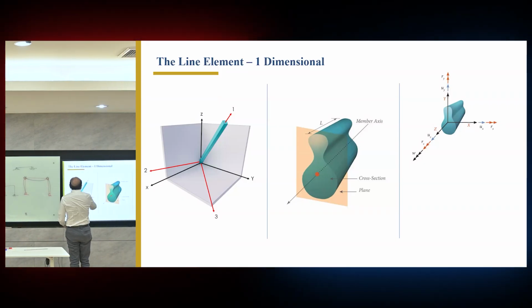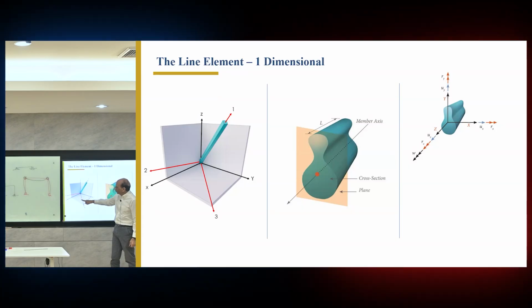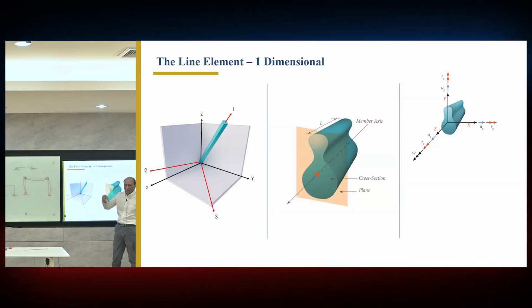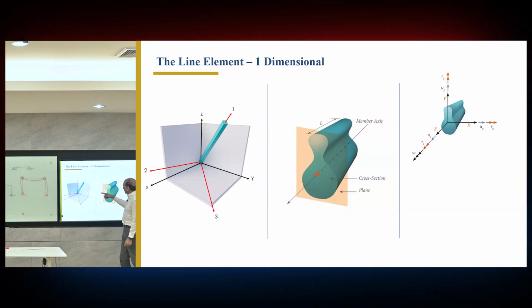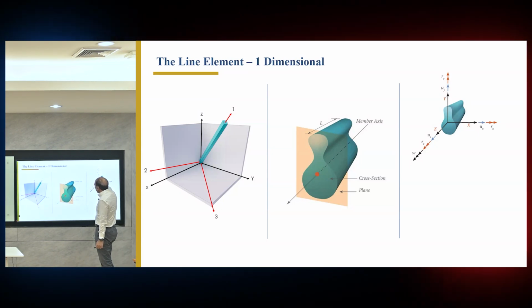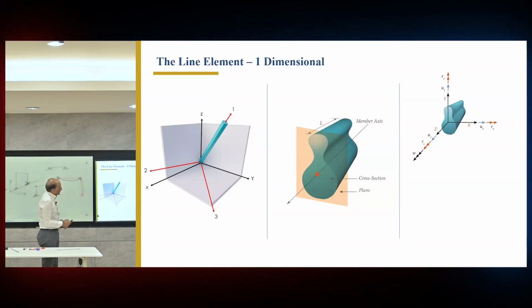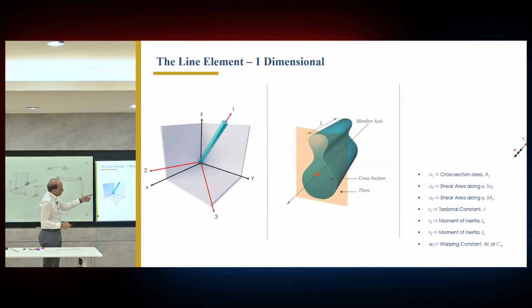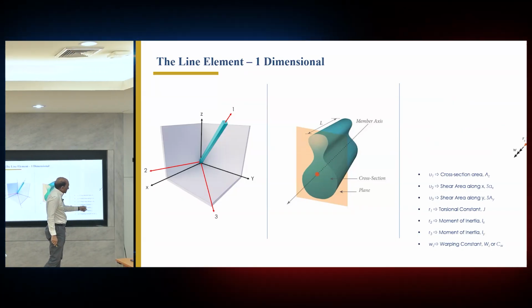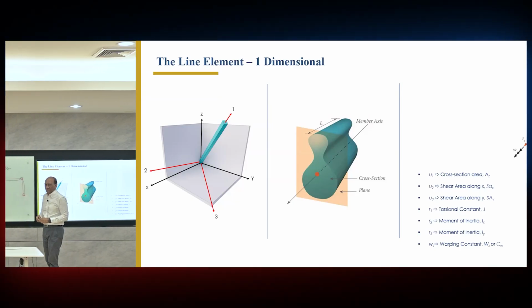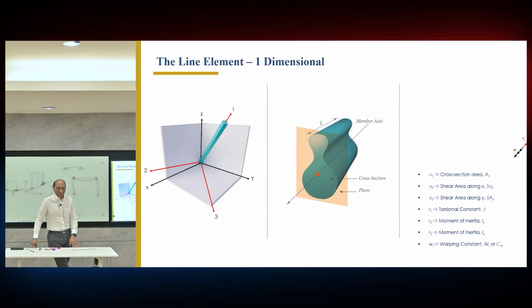So if you have a one-dimensional element, then its properties have to be oriented about 2, 3, because major properties, minor properties, which direction, how do you put the Ix and Iy? So that's why, you remember, we had this member axis, we have these 7 degrees of freedom, and we talked about them in the last course. And then we had those deformations, properties, and forces around 6 directions. So we studied this in the last course, and I told you at that time we'll come back to this.